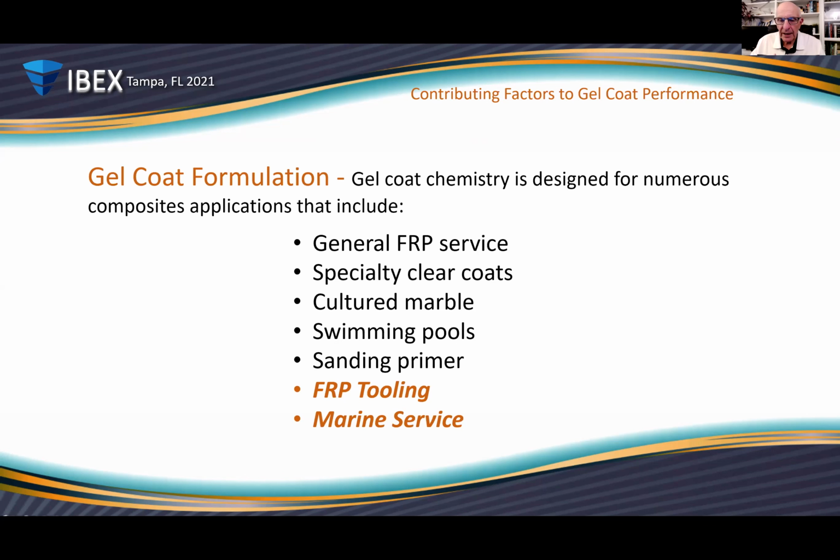So it's not a matter of just making the toughest gel coat possible, the highest modulus of elasticity gel coat, or making the shiniest gel coat possible. There's always a compromise in between. And various gel coat formulators make that compromise in slightly different ways according to their testing and the data that they've gathered on how their material is going to perform.